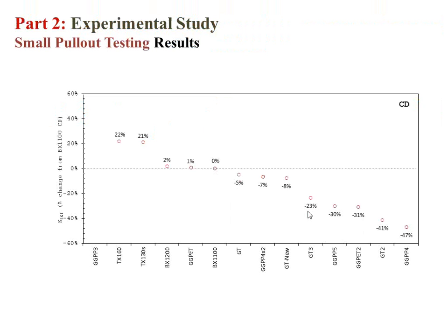If we're going to use this for design, we need to test the actual base with the actual geosynthetic. And that would be what we need for design. But we're never going to do that. We may do it, but essentially what we need for design is to compare different geosynthetics for whatever base the contractor ends up choosing.